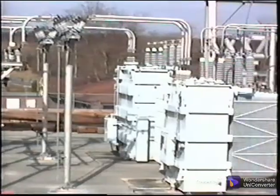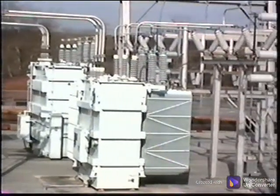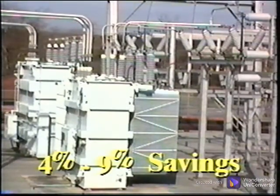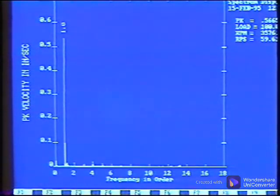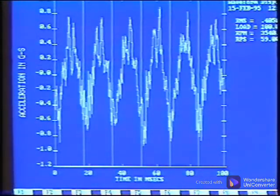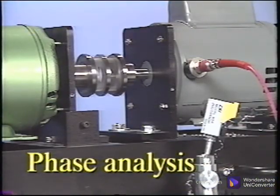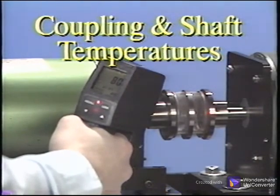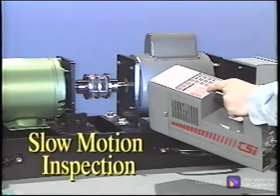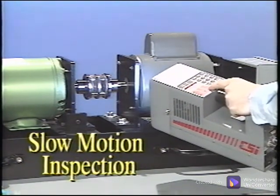In fact, studies have shown that machines properly aligned can reduce electrical power consumption by at least 4 to 9%. Misaligned conditions can be detected using at least 5 predictive maintenance methods that do not require an interruption of the process. They are spectral and waveform analysis of vibration data, as was shown earlier, phase analysis of vibration data. Another is to measure coupling and shaft temperatures using an infrared temperature probe or infrared thermography. And the strobe light can be used to actually see shaft, coupling, or machinery movement in slow motion.